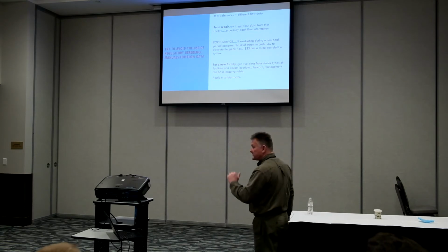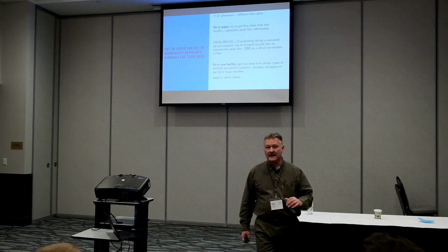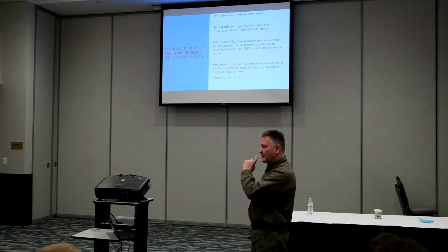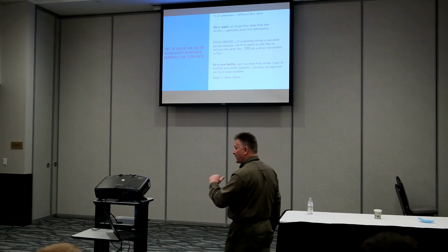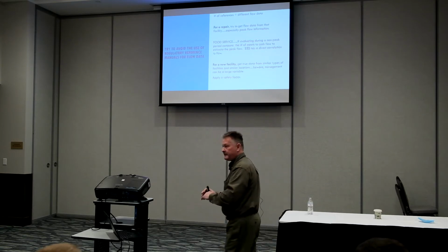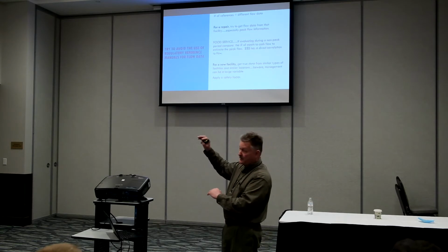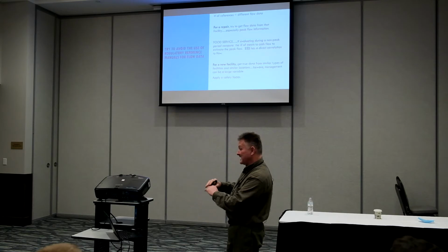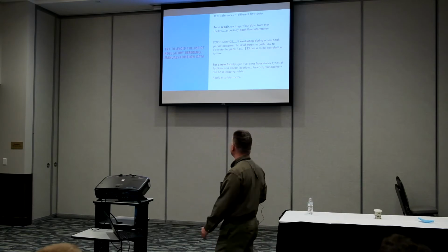Now, in a food service establishment, if you're evaluating that and it's during a non-peak, cash flow corresponds to wastewater flow. So you look at the number of meals during their peak. If during their peak periods they indicate we see a 25% increase in revenue, you can probably be pretty safe to assume we have a 25% increase in flow in those particular situations.